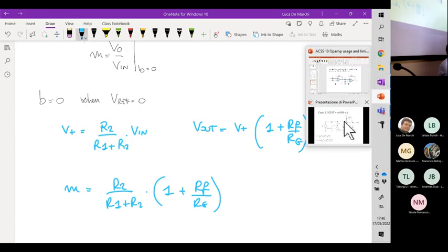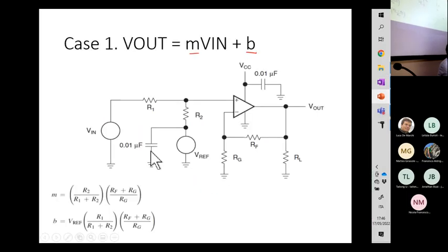By doing so, you can achieve the sizing of the elements of the circuit. Again, you can find here two capacitors. The role of this capacitor is to bypass high frequency noise in the circuit. So the possible instabilities of Vref are driven in this direction.